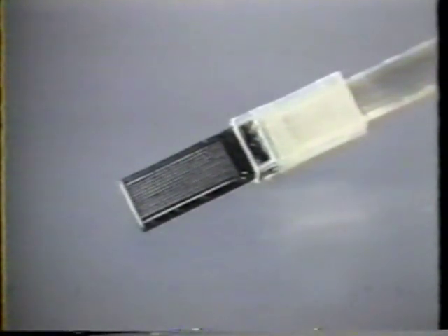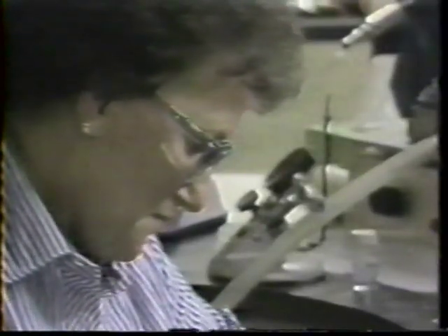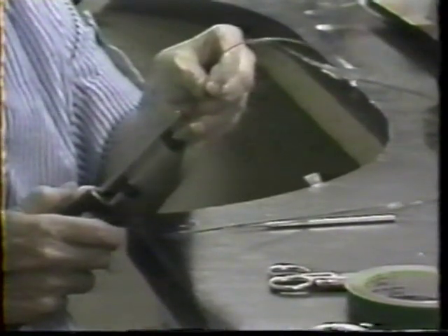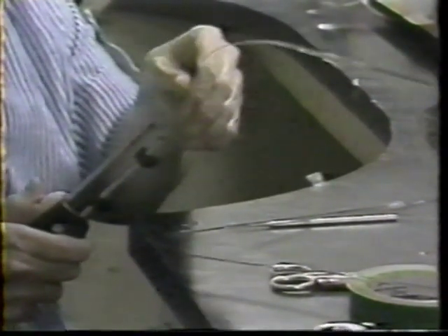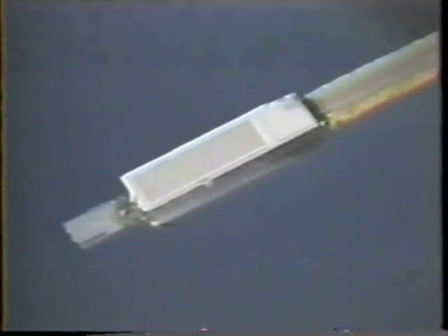Although similar in principle, the array connector uses an etched silicon chip designed specifically for the 12-fiber ribbon. A single multi-fiber ribbon splice is made by removing a portion of the mylar tape and fiber coating from the end of the ribbon and permanently affixing two etched silicon chips. Since these chips have been specifically designed to be used with multi-fiber ribbons, they consistently and accurately align all 12 fibers. These silicon chips are referred to as being positive chips.